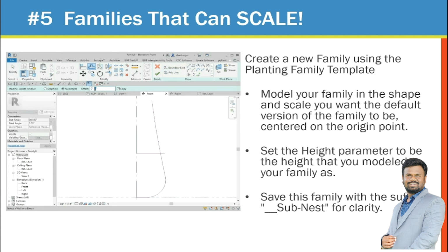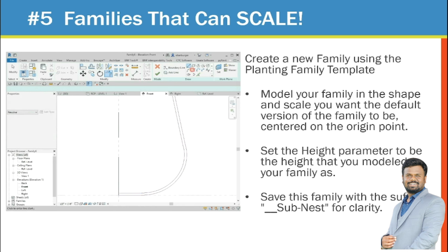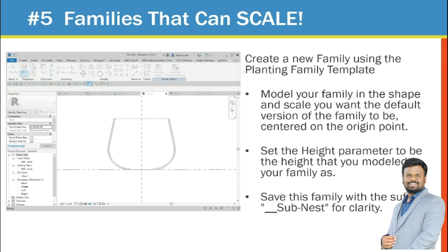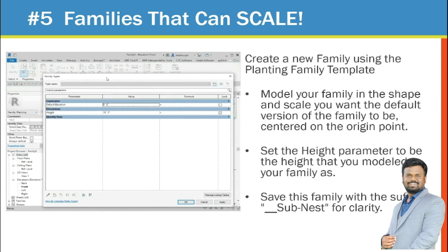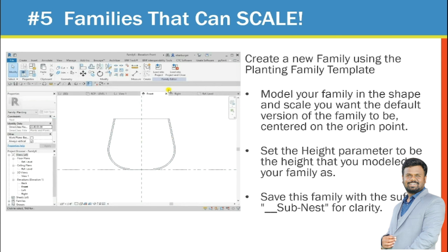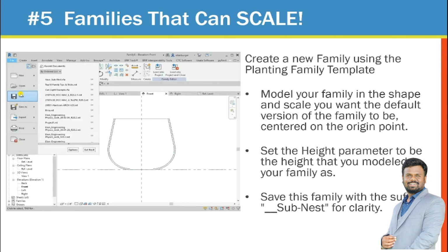But what we're doing here is I'm making like a little vase bowl type thing, so that final family will be an entourage family, because that would be the proper family category. So I'm just finishing the revolve here. And we'll see as we finish the shape that I would go into the properties of it, and the built-in height thing I will set to whatever the default height I want for bringing this element into a project.